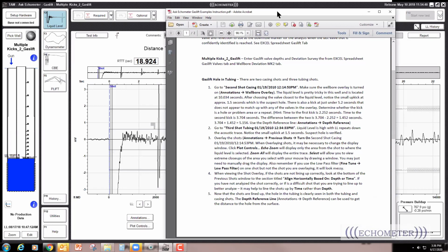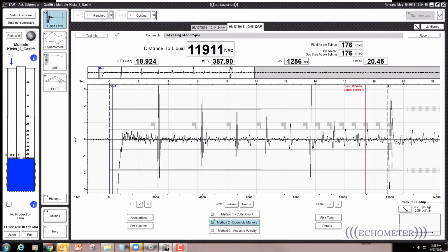So if you shut the valve to the compressor, that isolates the gas injection noise and the compressor noise, but you still will hear valve noise downhole. So I would try shooting it without shutting anything in at all. And if I then use a low pass filter, and I can see my gas lift mandrels and my liquid level, then I wouldn't shut the well in at all. The only time I shut the well in to shoot this fluid level is if I couldn't filter out the high frequency noise. So that would be my answer to the question.